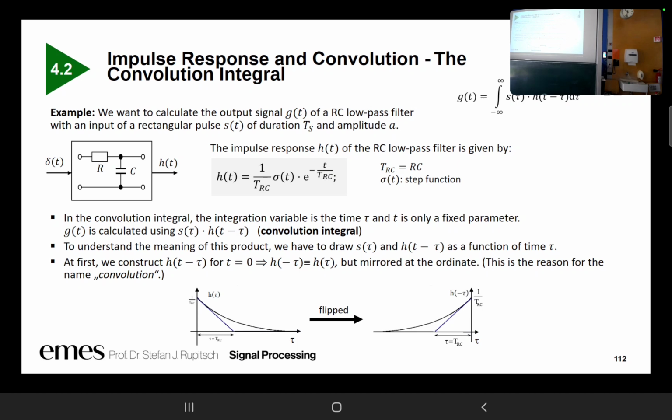What is a DC value for a capacitor in case of DC? Frequency 0, a capacitor behaves like an open circuit. And therefore, all the voltage which we apply in front has to be across the capacitor. But in our case, we put the pulse, and then the capacitor behavior is that we have this decay.